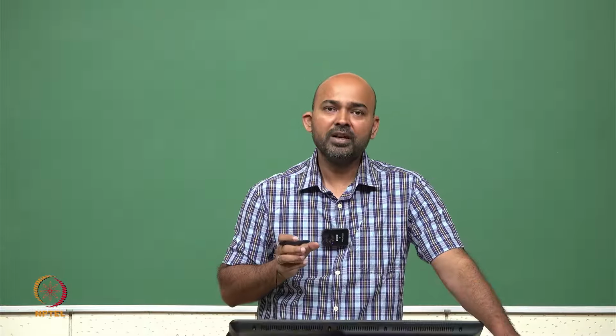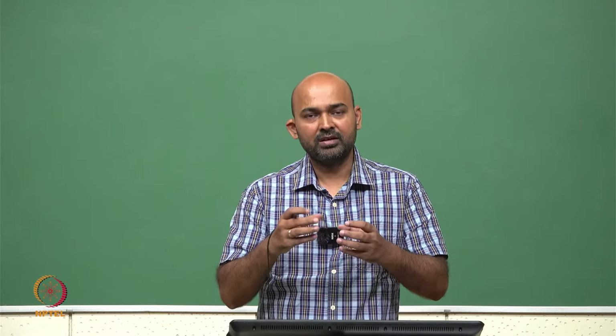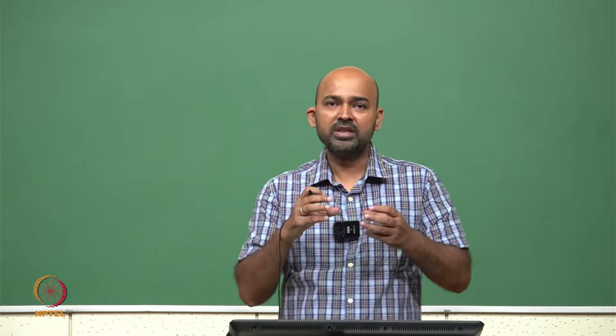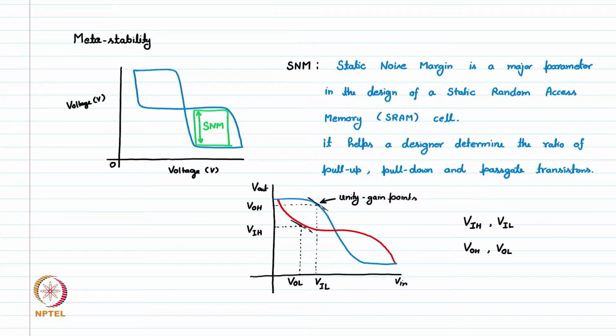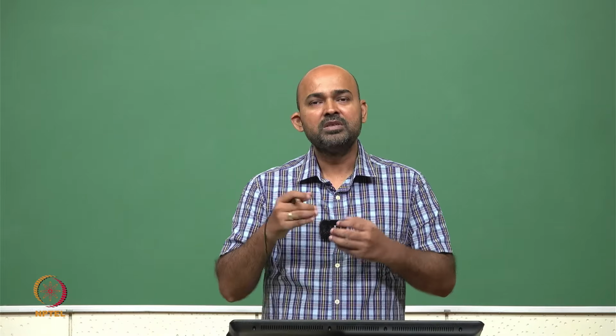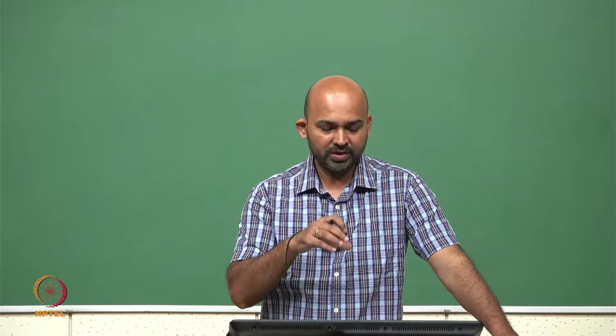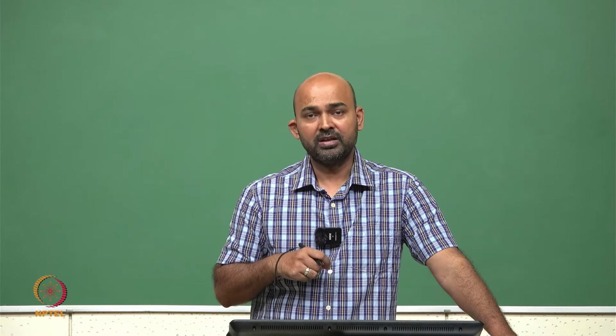These are very important definitions, and we will go through them after 2-3 lectures when we will discuss how we design a circuit using multiple blocks and connect them together. During the connection of these different modules, we pay very much attention to these VIH, VIL levels, because most of the time the error lies in interfacing these ICs or components together. That happens because of mismatch in VIH, VIL levels. So these are very important parameters which you can calculate from this butterfly curve.